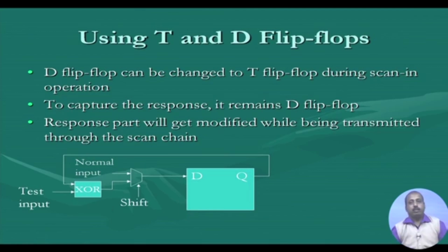So, the flip flop type is not changed. For the normal circuit operation there is no problem, that still remains as a D flip flop, but in the test mode these flip flops are converted to T flip flop.